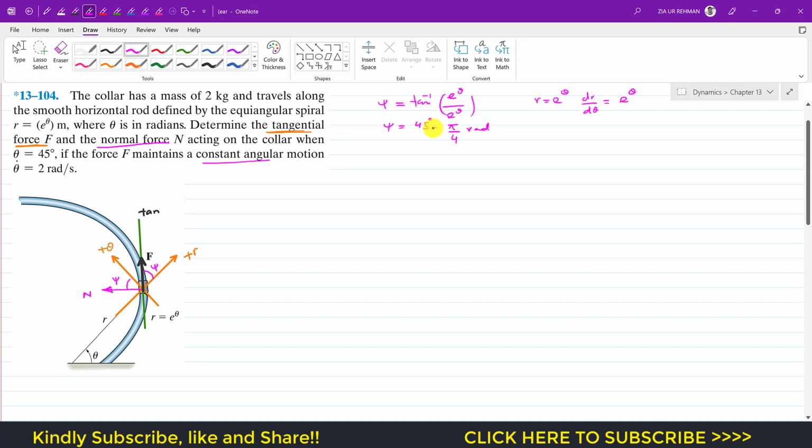So now we know that psi angle. If this psi angle is 45 degrees, and this normal is perpendicular to the tangent, this means that this angle is also 45 degrees, since this is that psi angle. So this is 45 and this is 45. Now we can resolve this N force into its components. It will have two components. One of its components is going to act in this direction. So if this is the angle, then this is the sine component. It will have one component which will be acting in this direction. So this one is the cos component, this one is the sine component.